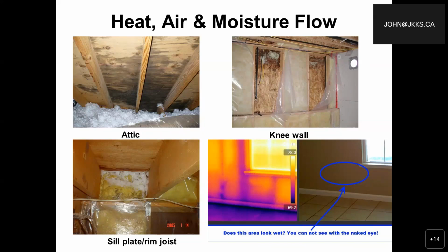And you can see I've removed a piece of the vapor barrier, the plastic vapor barrier. What we can see behind there is that white stuff, and that white stuff is really frost. Moisture has come in from the outside. Because this is a winter condition, we have warmer air in the basement and cold temperatures outside. We can see the movement of moisture that has frozen inside of the house in this particular instance.